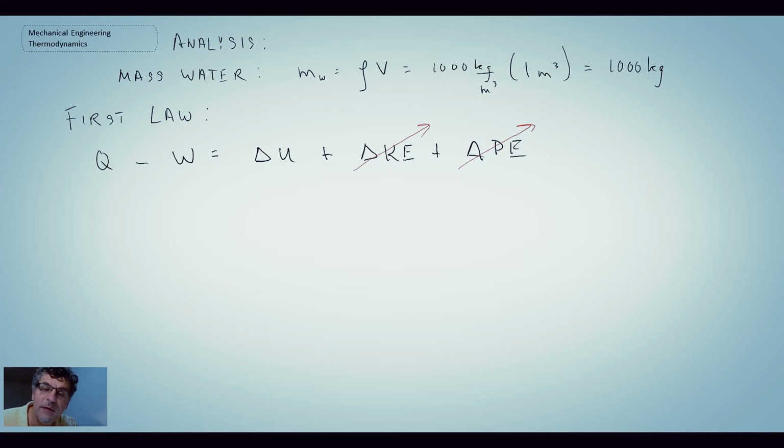And remember the sign convention for heat transfer into a system. If the heat flows in to the system, it's positive. And if the system does work, it's positive. In this case, we have heat leaving the system, so it's going to be negative, and we're doing work on the system, so that's going to be negative. So what we get is a minus Q loss plus work electric. It's plus because it's a minus term and then a minus W, that becomes a plus.